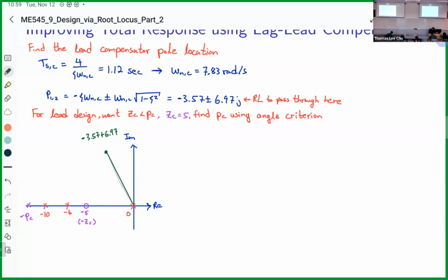So I'm going to now define all my angles. The textbook uses pole-zero cancellation here. Putting the zero at -6 makes it such that there are 2 less angles to calculate, which makes it a lot easier. You're welcome to do that on your homework. So we have theta 1, we have phi 1, theta 2. Sorry, I'm going to close the chat box here. Theta 3 for the pole at -10, and then theta 4 for our mystery pole.